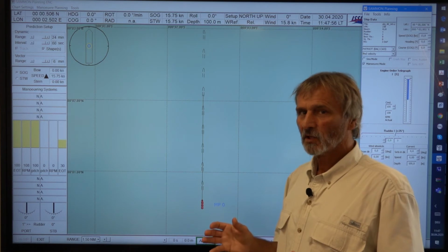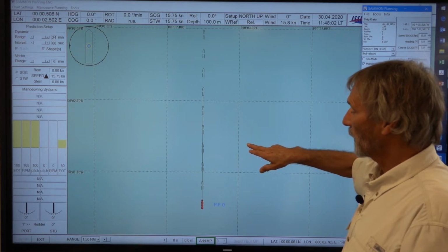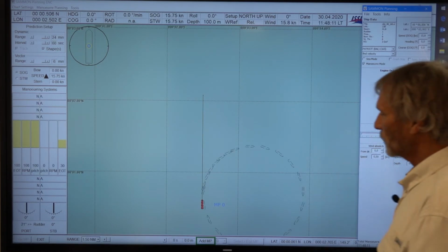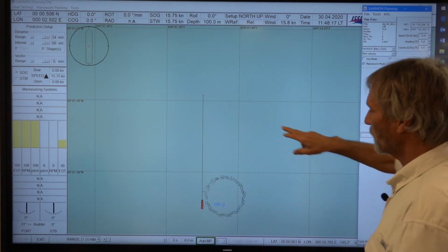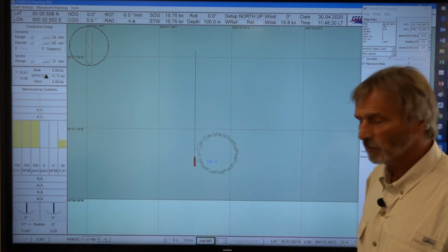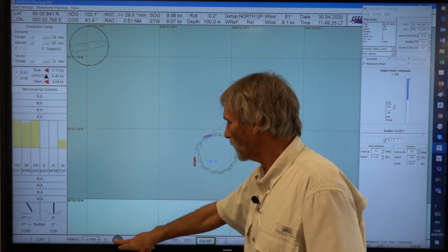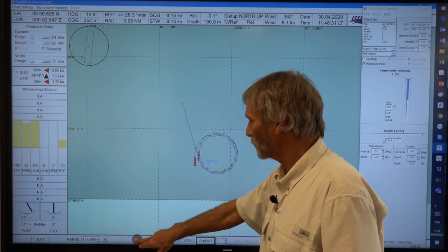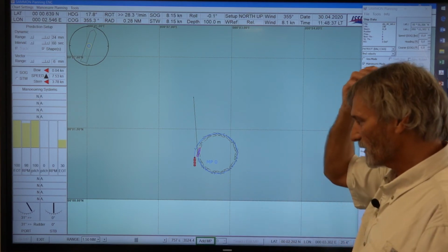So what other things could we do? There's a specific maneuver which is called the pull-out maneuver, and I will perform this for you. Pull-out means we use the rudder to about 20 degrees, maybe 35 degrees. So this is 30 degrees now. And the pull-out maneuver means you go into the turning circle, and after a certain heading deviation, we don't need to go for a full turning circle, but I will do it here only because we don't have to spend time for it.